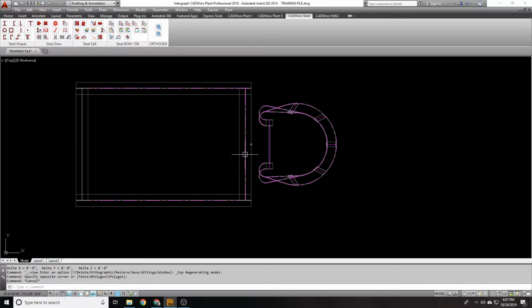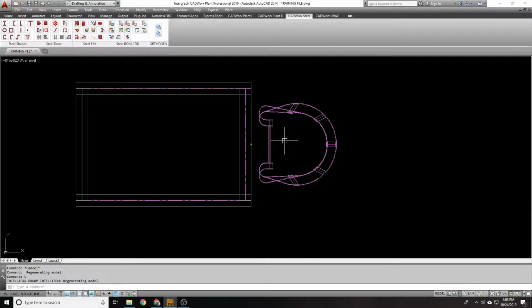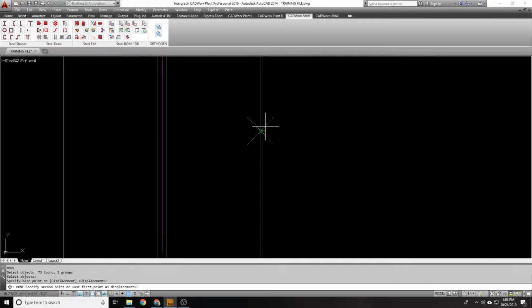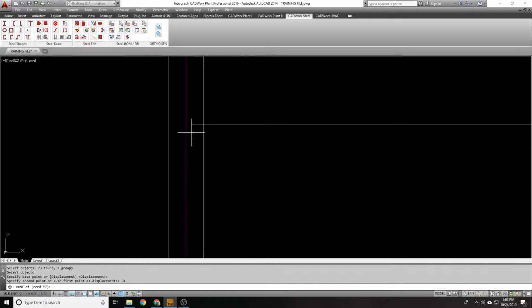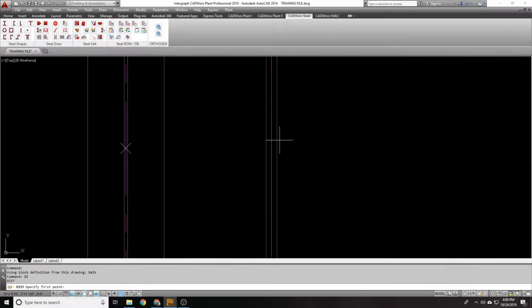All right, so what is it that I do? Why is it that I go to the center? So what I'll do, I like to stick around 8 inches for my clearance, but you need a clearance of around 7 inches to a foot. What I'll do is I'll take mine and I'll move it over to the center of the beam, and then I'll increase that offset distance to 10 inches. And this really just depends on the size of the beam that you're using. In this case, I'm using a pretty small beam. So if I measure from here to here, I've got 7 3/8. So I'm on the smaller side.